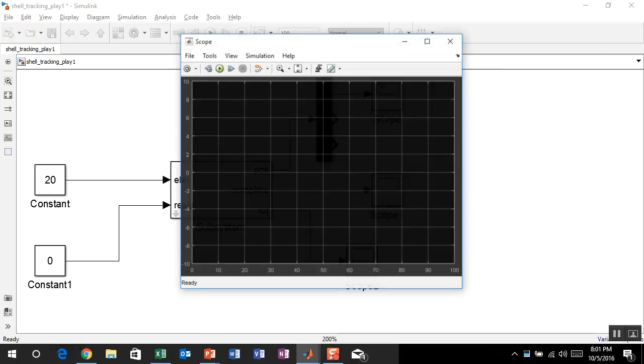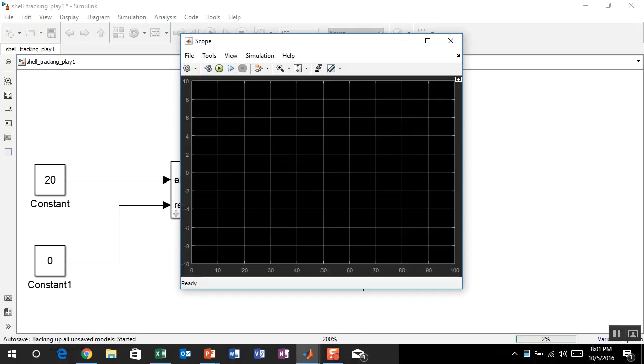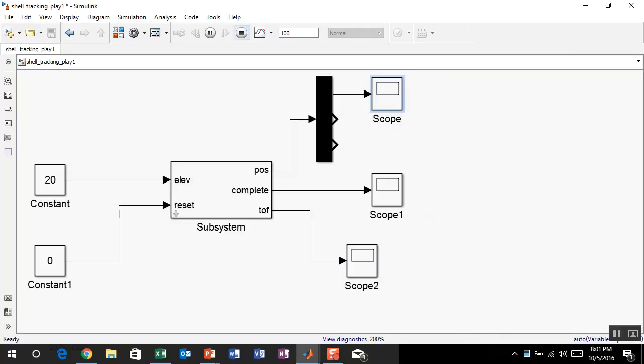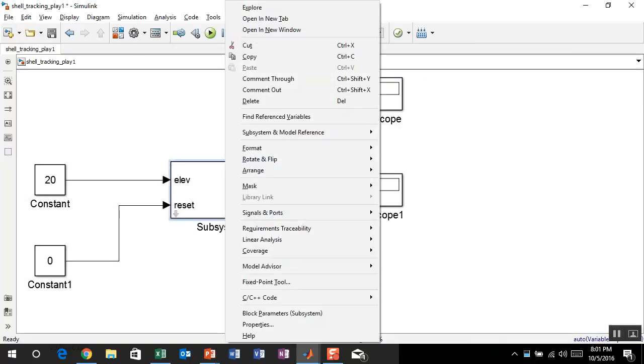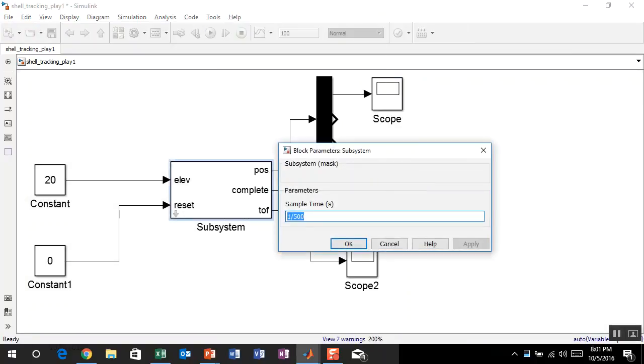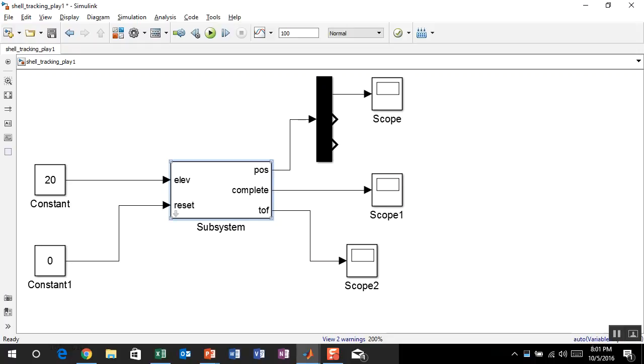All right, so let's run this. Oh, already messed up. We need to change our sample time here to be 1 over 2500, and we want to go 100 times faster than normal. Did I put the other? Yeah, I did. Okay. So this should solve in approximately 1 or 2 seconds. So that way we don't have to wait so long. So hit 1.